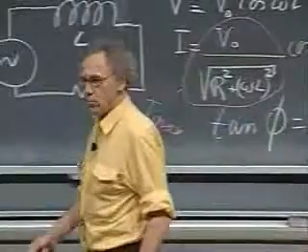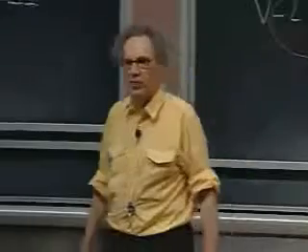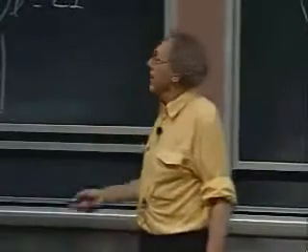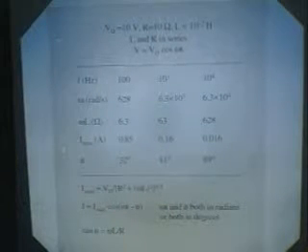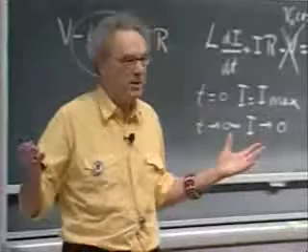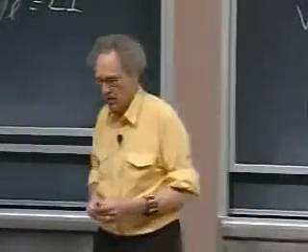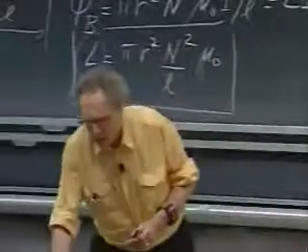I'm going to make you listen to music. And there will be violins which produce probably 3,000, 4,000, 5,000 hertz. And then I will turn on all of a sudden the 10 millihenry. So first I will make you listen to music whereby there is no 10 millihenry in there. And then I will turn on the 10 millihenry, and what you will hear is that the violins disappear. Because the current reduction is now huge on the high frequency, but is very little on the low frequency. And that's the idea of what a self-inductor can do for you. So if you listen to this,